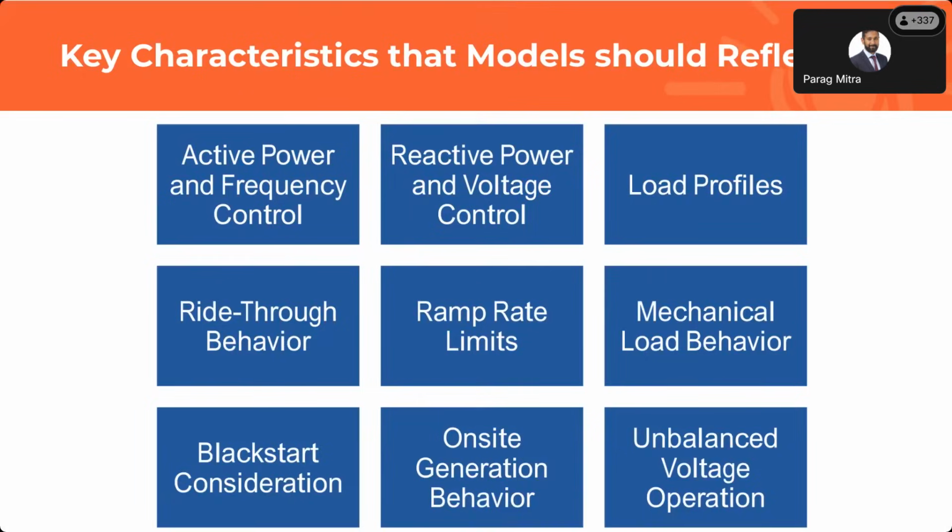So what are the key characteristics that some of these load models should represent or have so that they are good for some of the studies? And we won't get into a lot of great details over here, but I've highlighted some of these key items that one needs to make sure that the load models actually represent. So they should have a representation of the active power and frequency control if that exists, if the device participates in frequency control. They should have a good representation of the reactive power and voltage control.